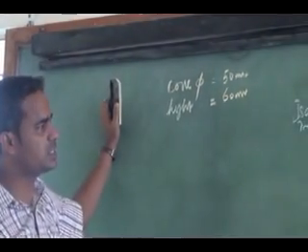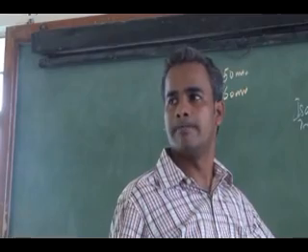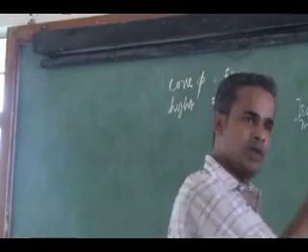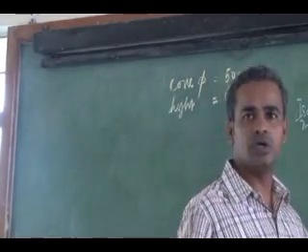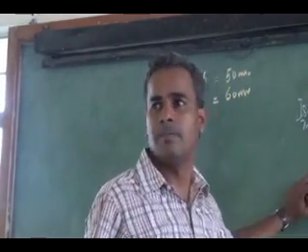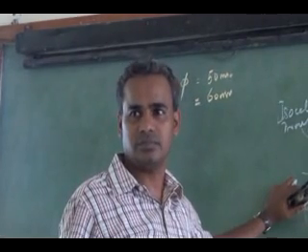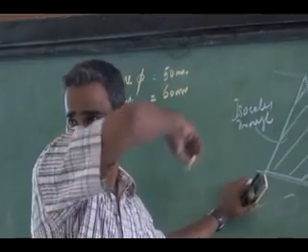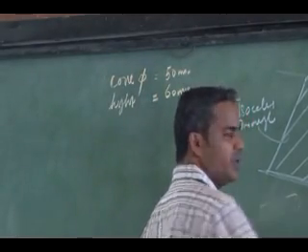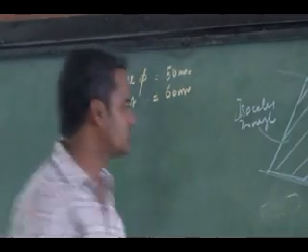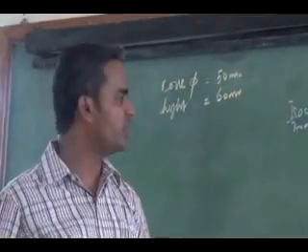It is cut by a cutting plane which is perpendicular to VP, passing through the apex, and inclined at 65 degrees to HP.